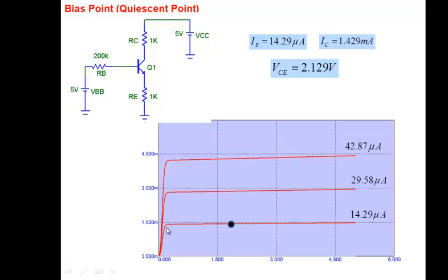What is the characteristic of the saturation region that you've seen here? The collector emitter voltage is almost a constant. If it is a constant, and you're making an amplifier and taking a voltage gain at this particular point, it means you cannot get a gain, which means this voltage does not respond. We'll see very quickly now that in the saturation region, your transistor cannot amplify. It's only in the active mode that the transistor can amplify.